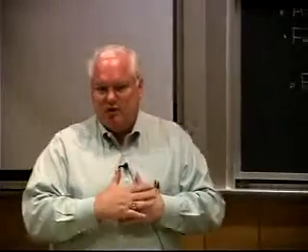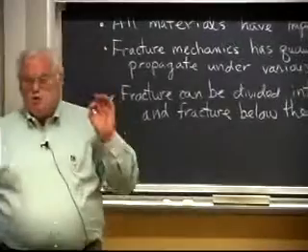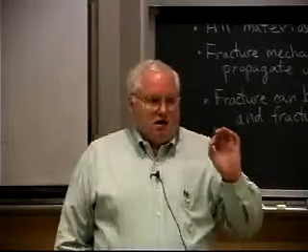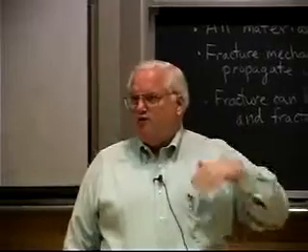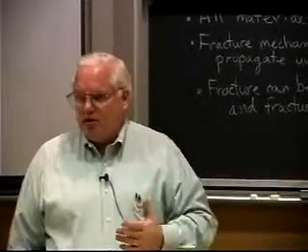And people try to use acoustic emission. The real problem with acoustic emission is there's a lot of other sources of acoustic emission, or noise. If two parts slide against each other, they'll generate noise. And it's not necessarily just cracks opening up. In any case, this was about 10 or 20 years ago. The U.S. Air Force decided they wanted to intentionally put a known size flaw in the structure of an aircraft and fly it, and use the sensor to see if they could detect the crack growing.